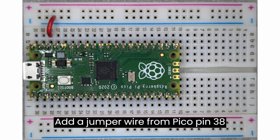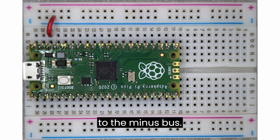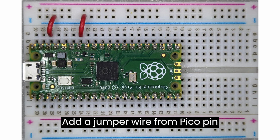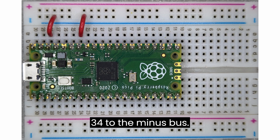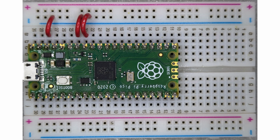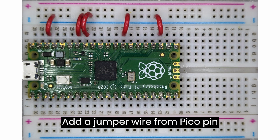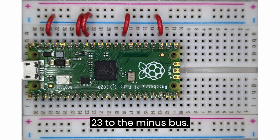Add a jumper wire from Pico pin 38 to the minus bus. Add a jumper wire from Pico pin 34 to the minus bus. Add a jumper wire from Pico pin 33 to the minus bus. Add a jumper wire from Pico pin 28 to the minus bus. Add a jumper wire from Pico pin 23 to the minus bus.